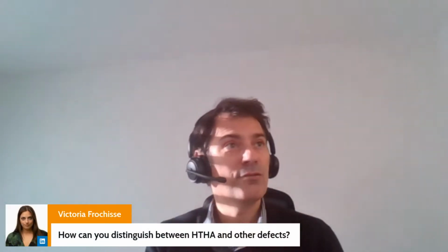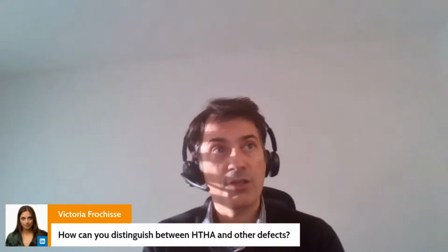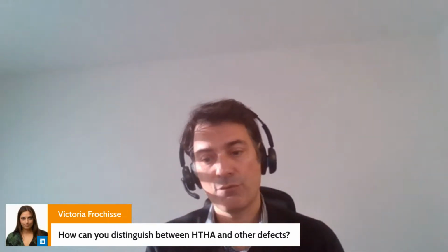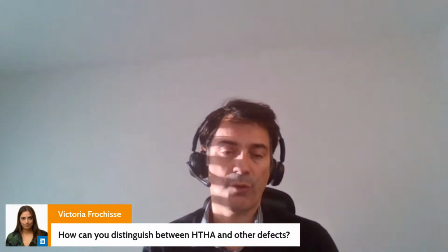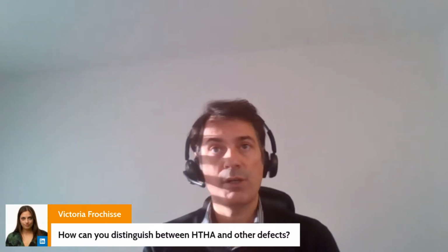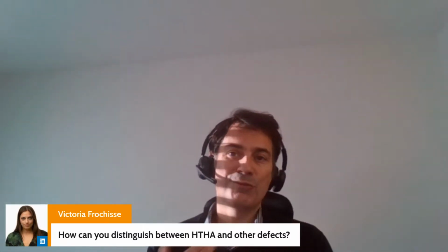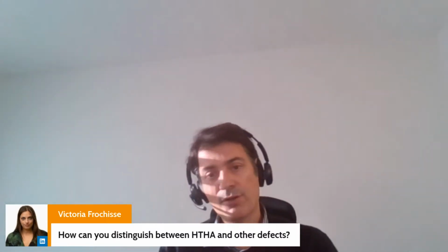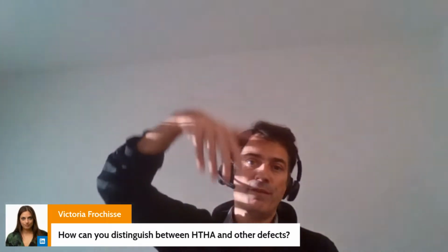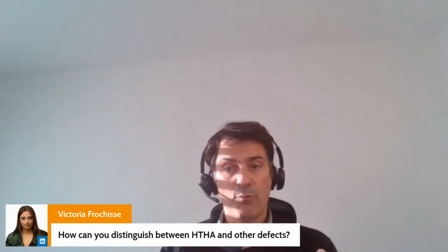Hey Victoria, can you distinguish between HTHA and other defects? So that's very often a question that comes back because, as we become very sensitive to these small defects, we also become sensitive to grain noise and to other things. So that's why, when I conclude, I say you need to know your asset. For example, let's say you have some porosities with laminations that are going to appear horizontal. So when you fire at 0 degrees, you're going to see them very nicely, and you can confuse them with HTHA.